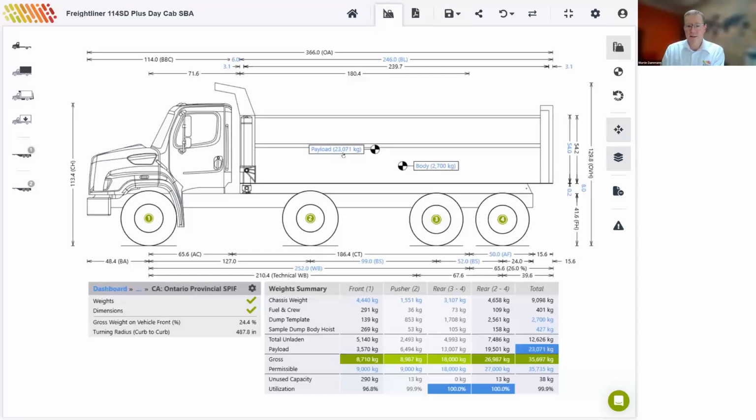Nevertheless, we've got about 7 tons more payload on this vehicle compared to our baseline vehicle. Remember, we've gone from 16 tons up to 23 tons. So that is a pretty good overall result. In terms of turning radius, both the set back and set forward axles should produce about the same results because they both have a wheelbase of 252 inches.